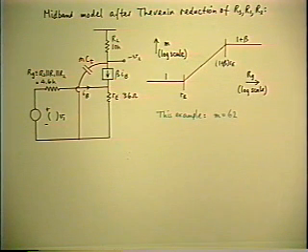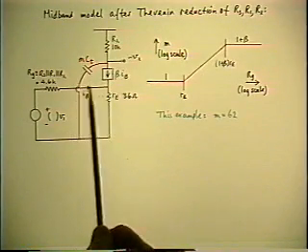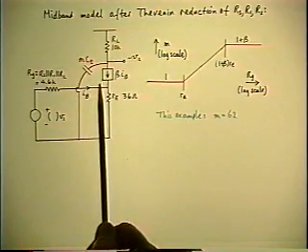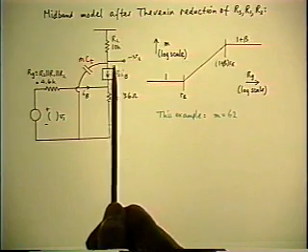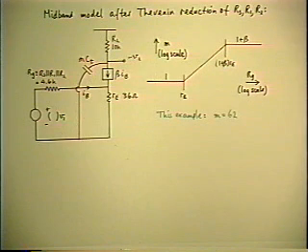So you've got to be a little careful about equivalent circuits. Equivalent circuits give the right answer by definition. That's why you make them. I said that already. But you've got to be careful. What is the answer you're looking for? An equivalent circuit can give you the right answer for one function, but not for another. So you've got to be a bit careful when you make this transformation related to the Miller effect, by remembering that it only gives you the right answer for the gain of the stage, not for any other properties.